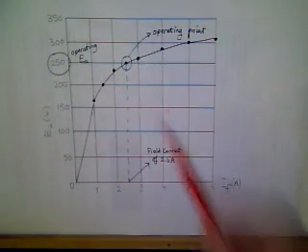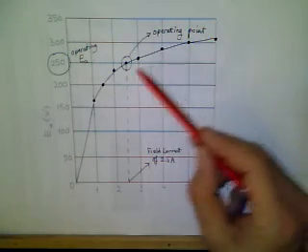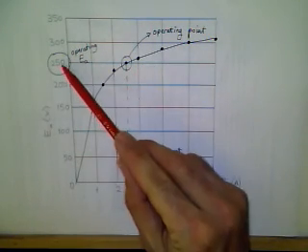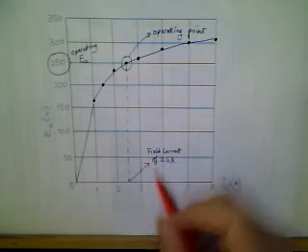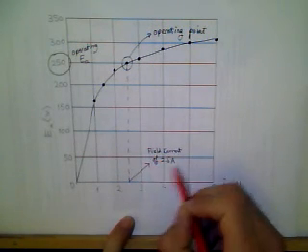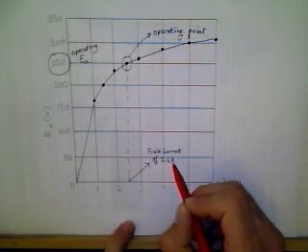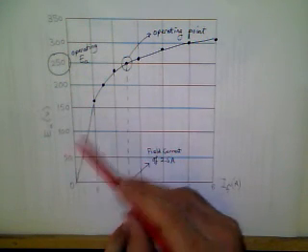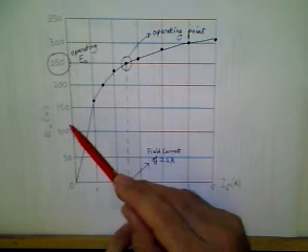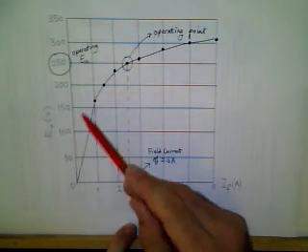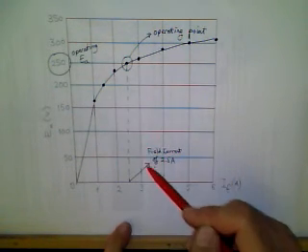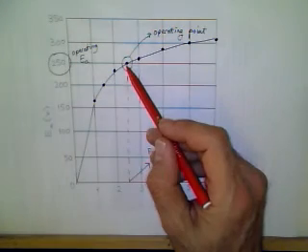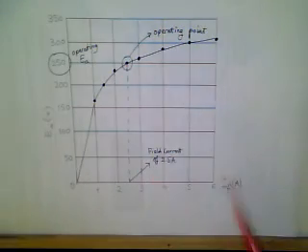So if we summarize, in the magnetization curve, this is the point of induced voltage, and from this curve we graphically determine the field current, about 2.5 amperes. That's the reason in the field circuit our external resistance is 10 ohms and field resistance is 30 ohms, so total is 40 ohms. So this is our operating point for this problem.